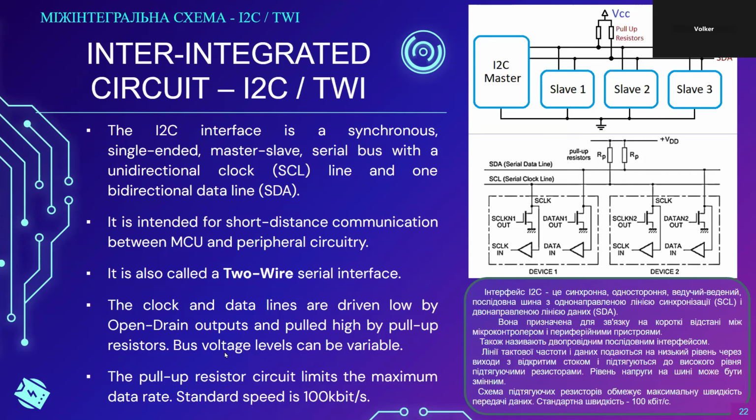I had mentioned that onboard and offboard usually means the noise environment is under the control of the developer, of the circuit designer. As long as the cable, the wiring environment remains under the control of the designer, short off-board connections are relatively common for the I2C bus.